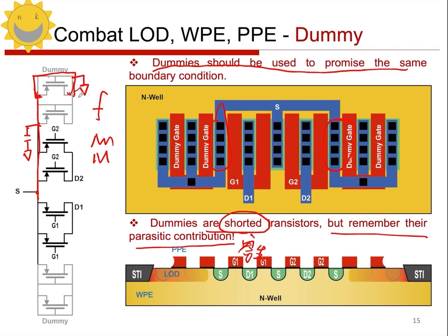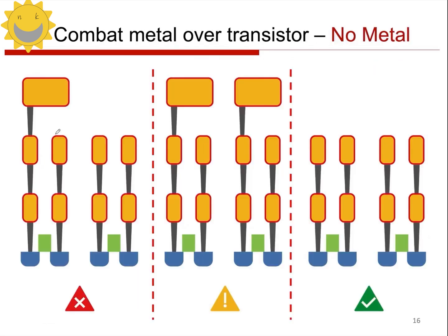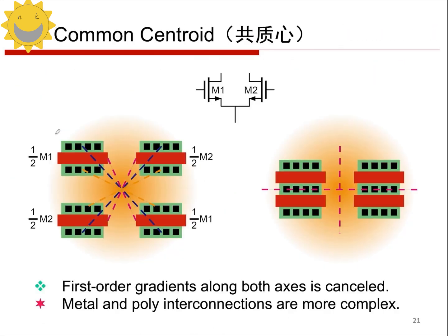Of course, it does not mean that it must be done this way. If I'm not sensitive to the source parasitics, right, then the size of the parasitics doesn't really affect the characteristics of my circuit much. In that case, you can connect this round end to this one using the finger method. That's fine. However, if you're sensitive to parasitics and can't have large parasitics at the source end, then you need to consider whether to break this unit apart, right? So what does it mean to break it apart?